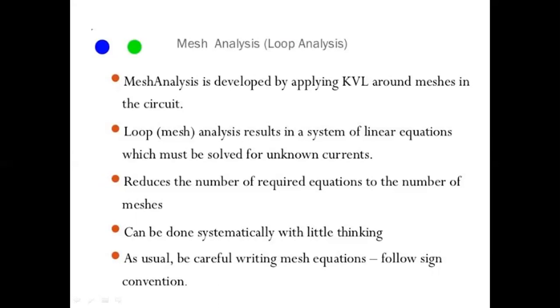So mesh analysis or loop analysis. This analysis is developed by applying KVL around meshes in the circuit. The loop analysis results in a system of linear equations which must be solved for unknown currents. It reduces the number of required equations to the number of meshes, and can be done systematically with little thinking. As usual, be careful writing the mesh equation, follow sign convention. For this case, sign convention is very important.